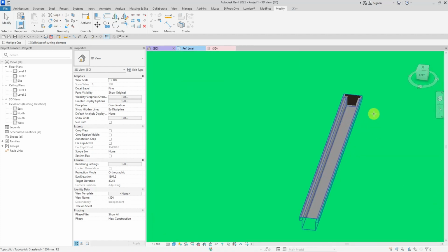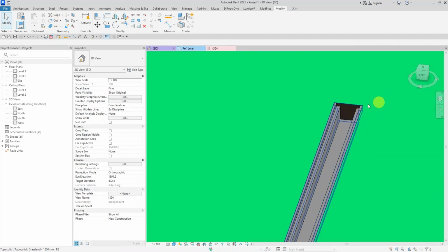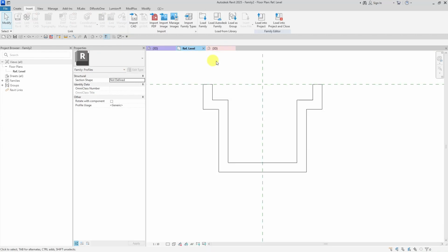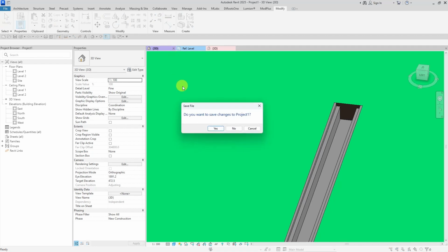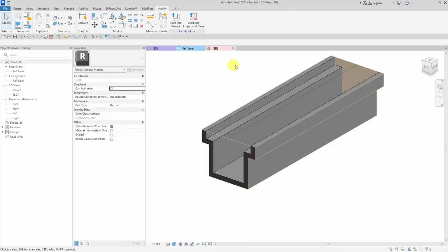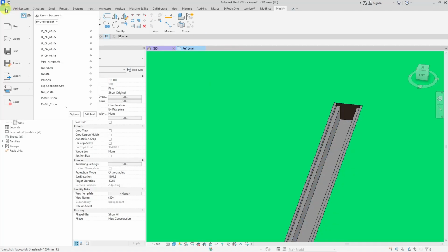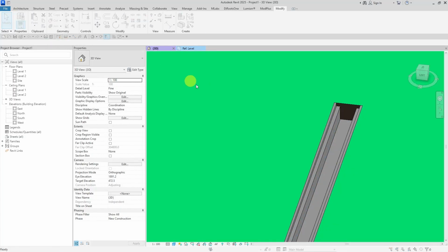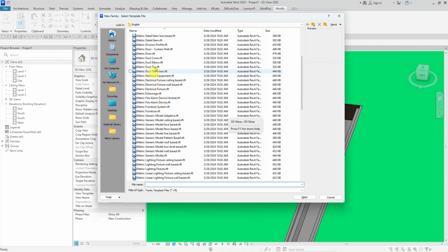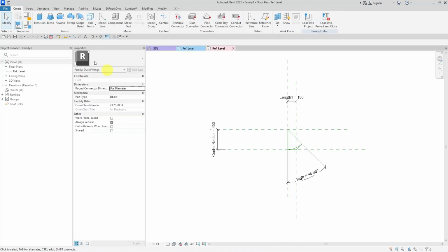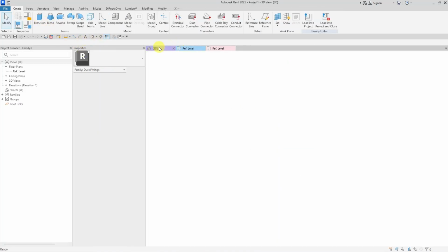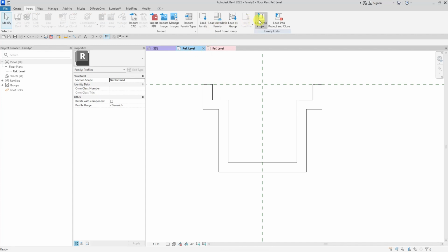It will be cut here, but the important part is the curving part. The main and important part of course is here. Let me close this environment, and for the curving, we can use a really interesting technique. We can use the duct elbow, duct cross, duct T, and such examples. Let me just select a duct elbow here, and then I will load this profile.